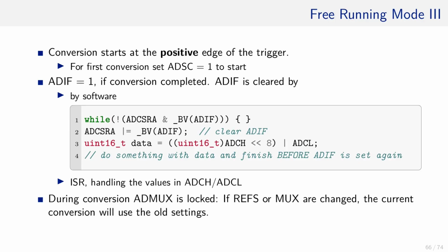The ADIF bit is cleared like in this scenario, followed by the data being read from the data registers. Imagine that the data is then communicated through a slow communication interface. Hence, we will not return to this code section on time to read the next sampled data, but we might skip some readings.